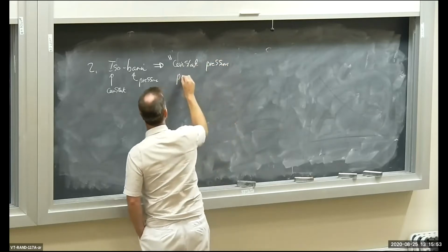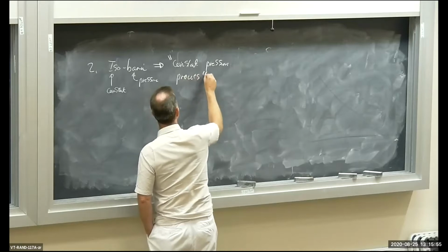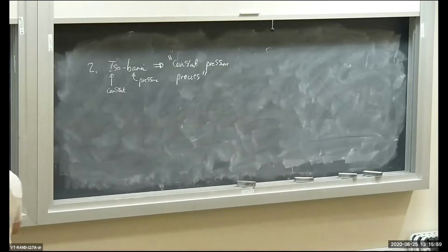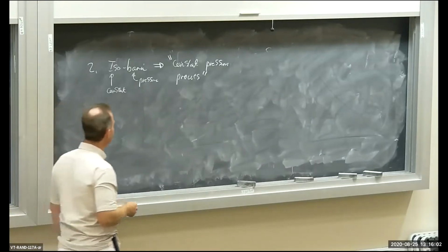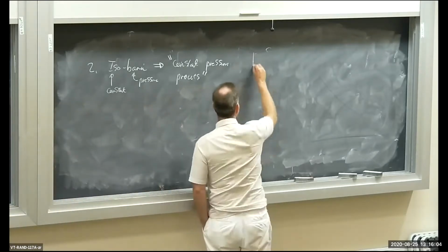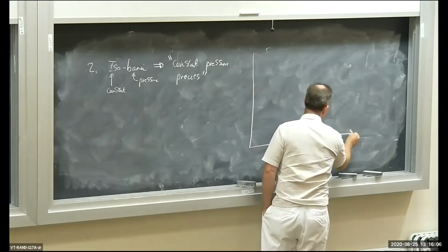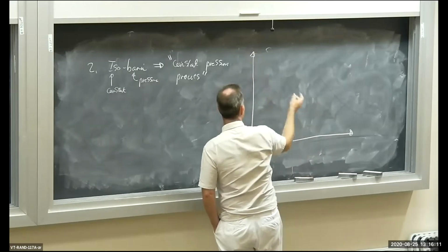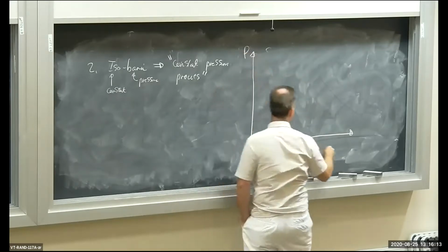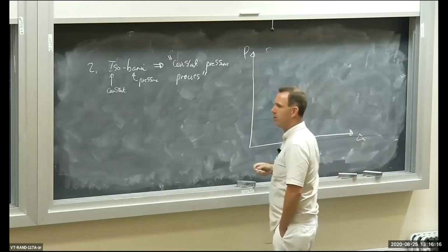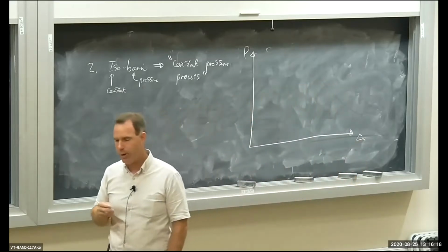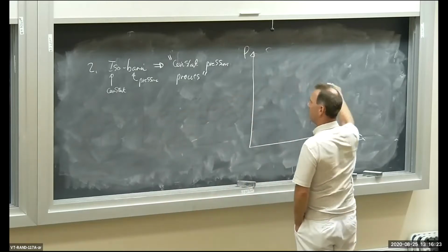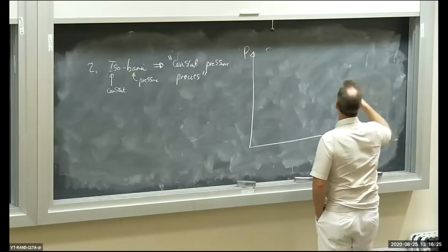Constant pressure process. So again, I could have a piston cylinder device of some kind. I could take a gas or something. And instead of having temperature and volume here, I could have pressure and volume. So on a PV or pressure volume plot, isobaric processes will be horizontal processes on the plot.